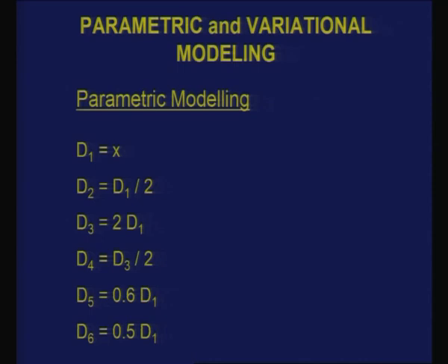So, what has happened is, together with the designer's intentions or constraints, the parameters which were 6 have now reduced to just 1. Given a particular value of x, which is the width of the object, both its shape and size are fixed. If I take care of these constraints as part of my definition, it is usually called a parametric definition. The solution is done sequentially, starting from 1, 2, 3, and they are also prioritized.